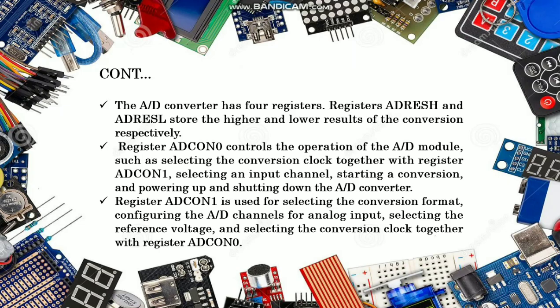ADCON1 is used for selecting the conversion format, and ADCON0 is used for selecting reference voltage and clock conversion.